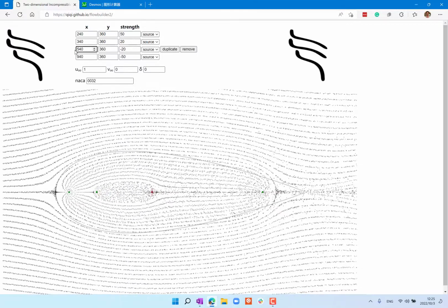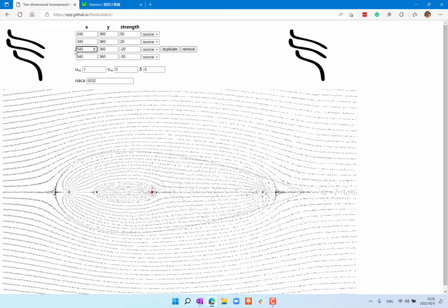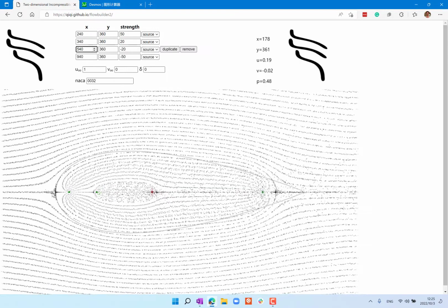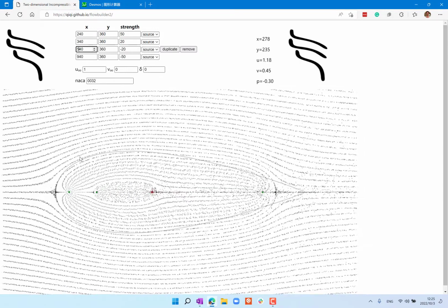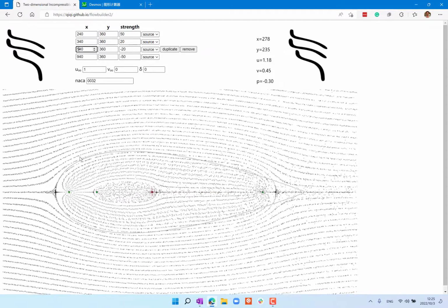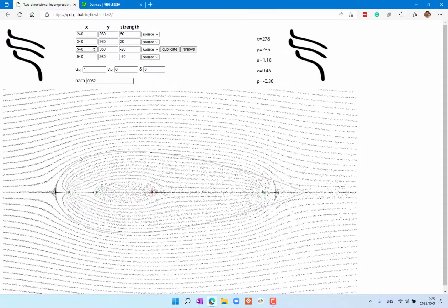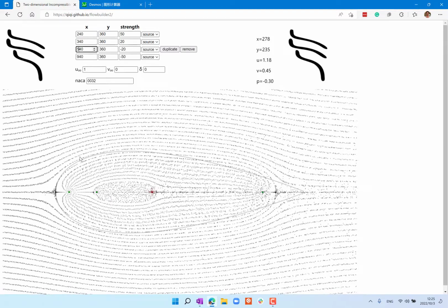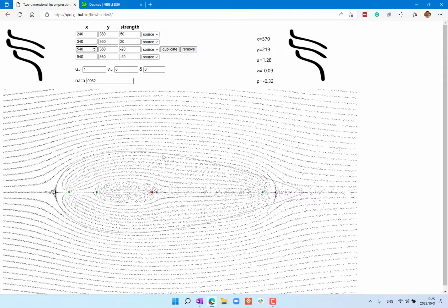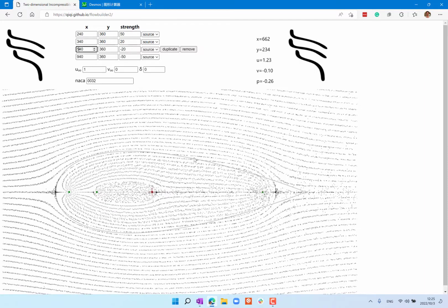But once you're able to do that, we can really interrogate the whole flow field to get all the pressure distribution, right? Of course, here you get stagnation pressure 0.5, and over here you get a pretty big suction, right? You all know the pressure coefficient CP, right? The CP is basically this value divided by the stagnation pressure, which is one half. So here you get a CP of minus 0.6. And over here, the pressure would recover, right? The CP is less negative.